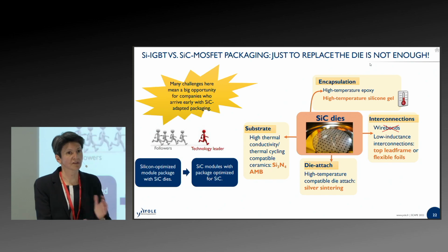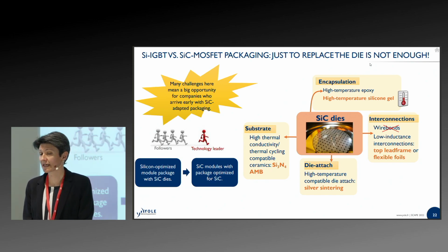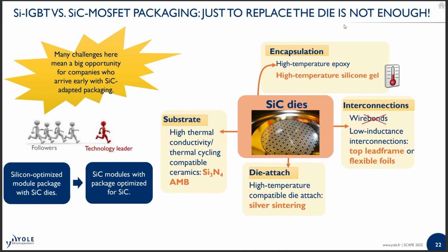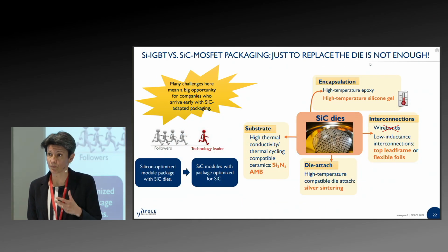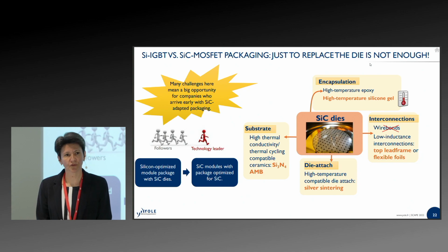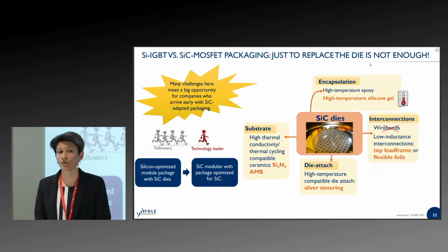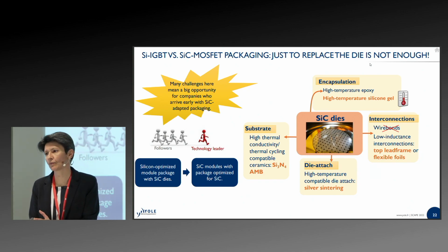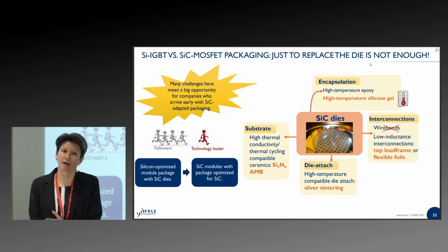Just a few words on technology. There has been a lot said, but in the past we were discussing with a lot of our customers looking into silicon carbide, and they said, okay, I'll just plug it in instead of using an IGBT. As you all know, the story is a little bit more difficult, or even much more difficult than that. Replacing the die will not be enough. You really have to reconsider your full power module, especially when we come to high power applications.